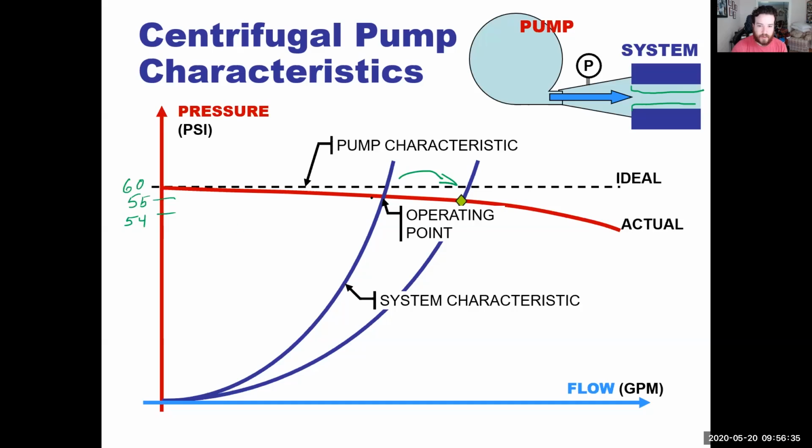All right. From just getting a little bit more flow, say we're getting 100 gallons per minute, and this boosted us up to 120. All right. But just a little bit of a loss of pressure. And that was just opening up the valve a little bit more, or maybe we cleaned out a heat exchanger. Because that's all that can be happening. So you clean out a heat exchanger and all of a sudden you're having proper flow going through it.